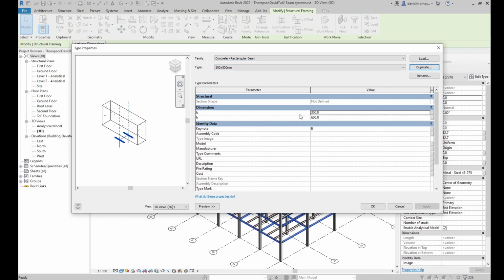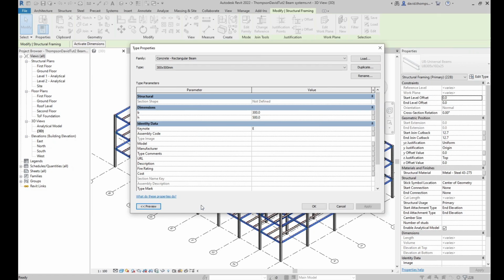We're going to actually have to change the dimensions. So we have the 300 here, and we're going to change the 500. So just type in 500 where it was 600. Let's click out. Before we do that, no, we've done the duplicate, sorry. Just double checking myself, and I think we're good. So if we click then, we'll see that's now the 500, and this is now the 300. And that's turning off the preview. You can turn it on and off if you like.